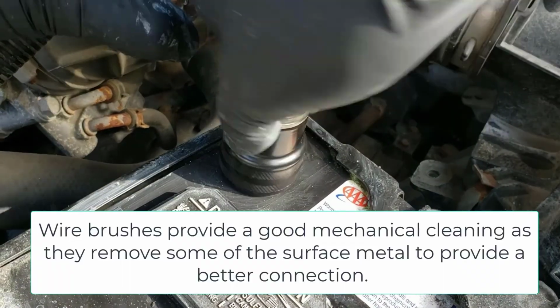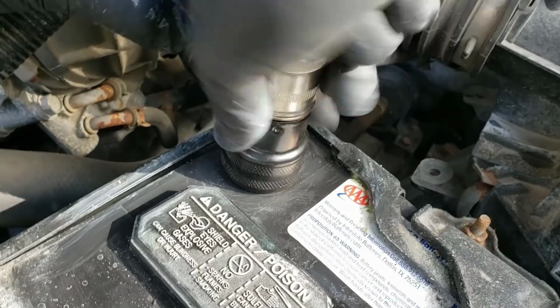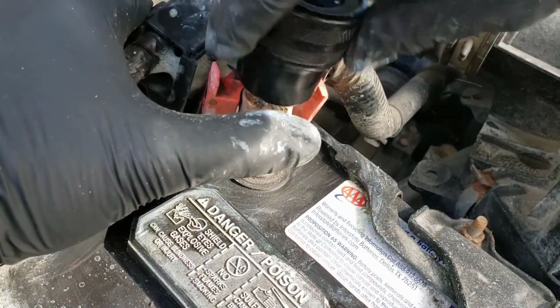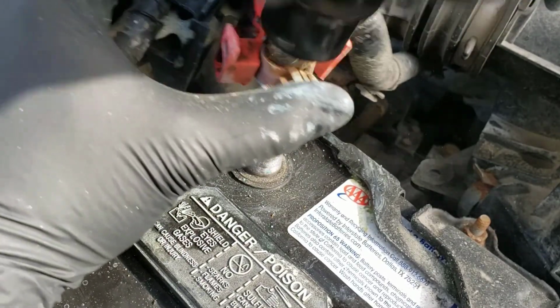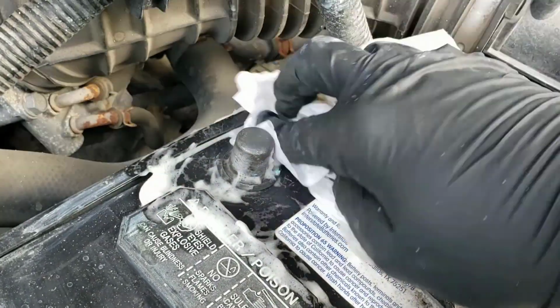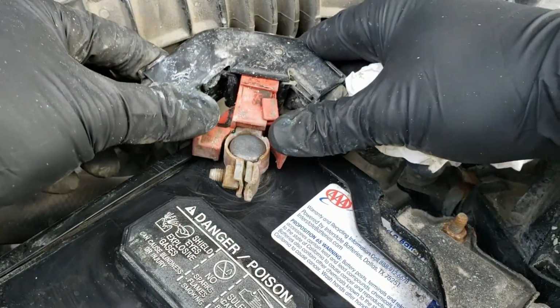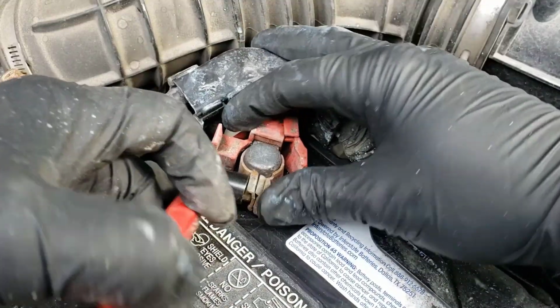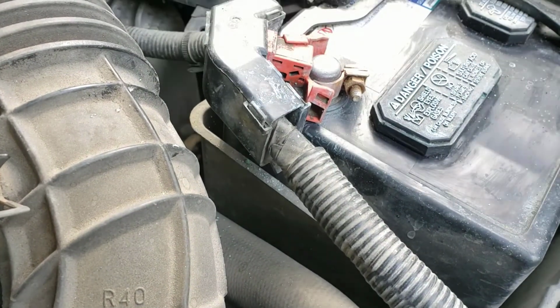I'm actually going to take a mechanical brush and scrape down a bit of the lead post. And right here I'm scrubbing away at the actual inside of the terminal so that the two surface areas will be nice and clean, metal on metal, no corrosion. Reattach it. Once again, supporting the terminal with my hands, snugging it. Not too tight, but tight enough.